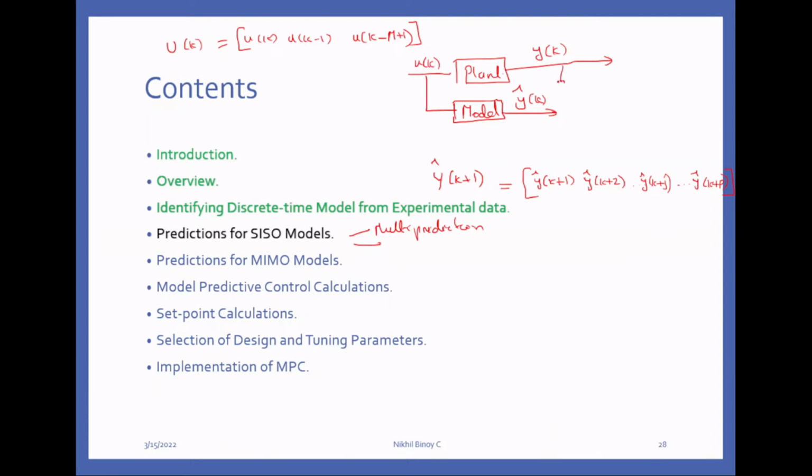So there is a difference between these two, where this is plus, this is minus. So by using this one, we can call it b. This is bias, the difference between these two, bias b of k plus 1, b of k. So using this b of k, we have to correct this y cap of k. So the correction of prediction using this difference is known as the corrected prediction. We have to label this one as the p horizon prediction. The same p horizon prediction that we have to modify by using this bias. That is represented by using y nu of k plus 1, which is corrected by using this b of k.